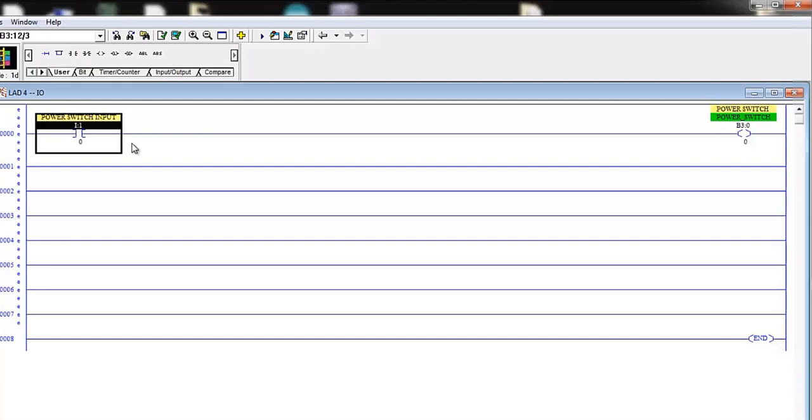So we will simply move that power switch to one of our spare channels, and that's going to require a program change. If your I/O is segregated and isolated from the rest of the program, you will have to make that change in one place. It'll be a 5-second change. You won't even have to test afterwards. It'll be ready to go. If you didn't set your I/O up this way, you're going to have a busy day.